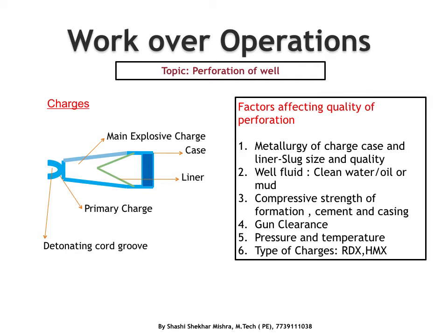Another factor depends on whether we are doing the perforation overbalance or underbalance. In underbalance, if we perforate, the well starts to flow immediately, which is quite effective in dislodging the debris of the charges and the loose crust formation, sands and so on.